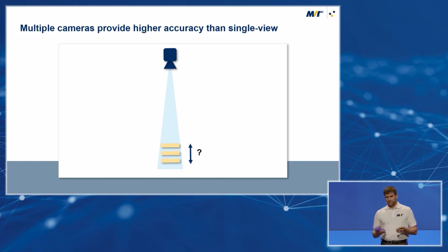And to pick it, robots are expensive, and also some parts also are really expensive, and we need to trust our machine. What can we do? We add a second camera. Now here, it's a triangulation model, and we can see easily that now the depth is not anymore a problem. We can find it very, very well. So we recommend using more than one camera, so 2 or even more.